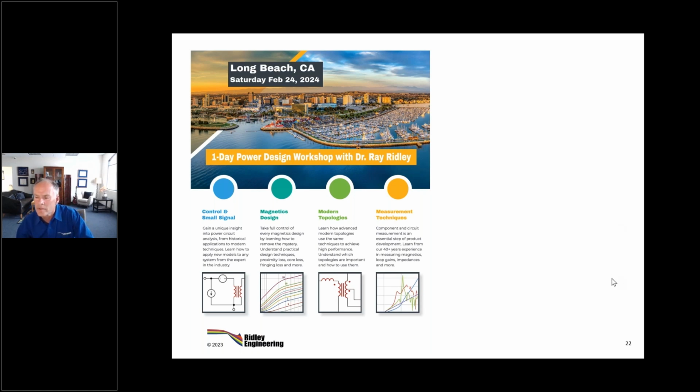Okay, does Ridley Works use Vorperian's PWM switch model for simulations? Well, it uses it for simulation of the loop. However, the time-domain simulation in Ridley Works is cycle by cycle. It's simulating the switch as you go. It does it about 100 times faster than LTspice will, because we've got our own simulation algorithm in there.